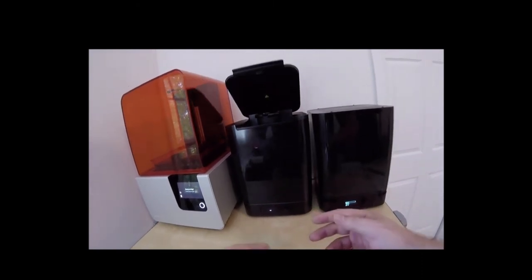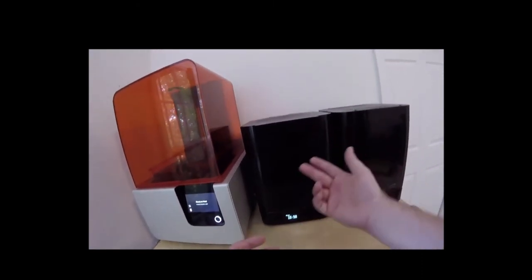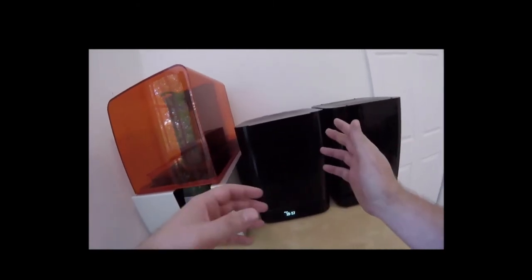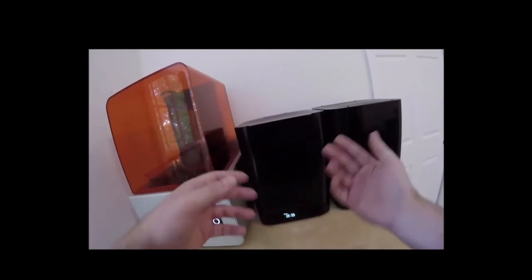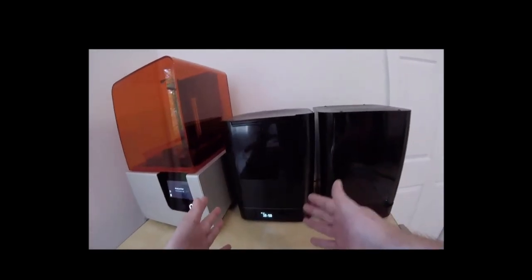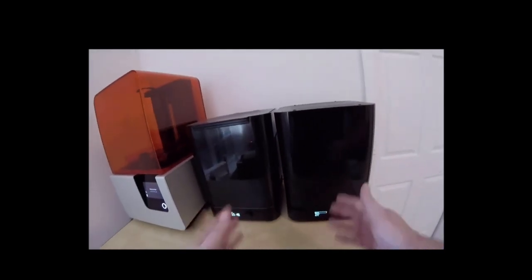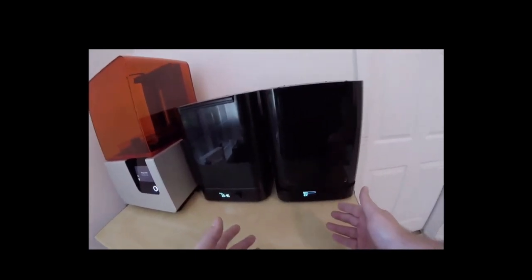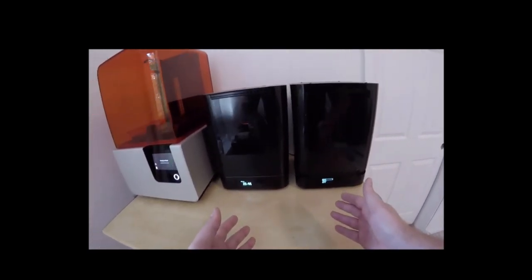While Form Wash is running, it's going to agitate isopropyl alcohol and wash the part. It is going to reverse directions every once in a while, so alcohol flows around both sides of the part. Once it's done washing, we'll move it into the cure. The cure takes a little time to heat up to 60 degrees Celsius. We're going to do a 60-minute cure at 60 degrees Celsius.